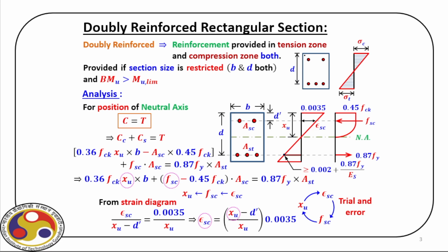Now, for this beam, again, we are familiar with the width and effective depth, right? That definition remains same. And obviously, if I remove these two reinforcement rebars, then what we get? A singly reinforced beam. And for that, we can find out Mu limit, that is the limiting value. Then if by chance my applied bending moment is more than that, as I said, we can go for a section having more effective depth and width. But a better solution is to provide these additional reinforcements.